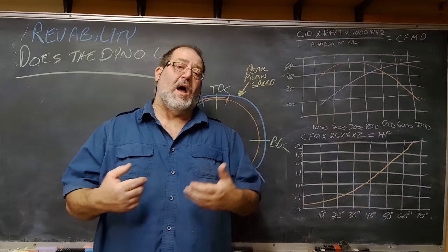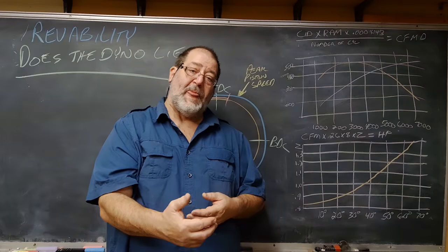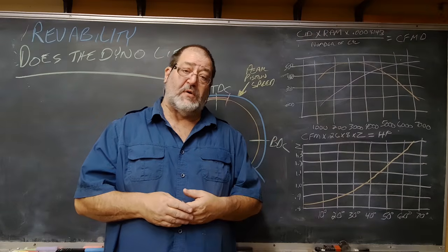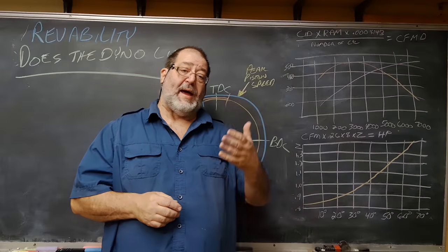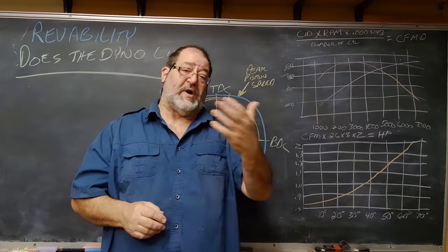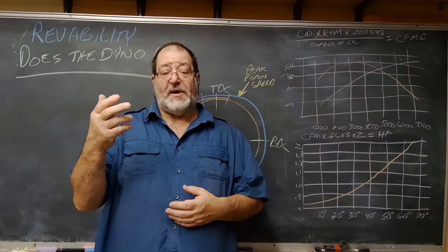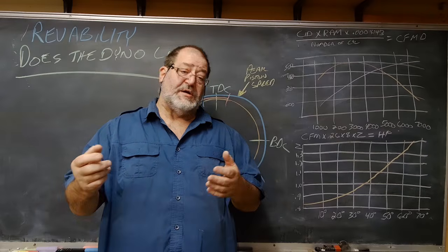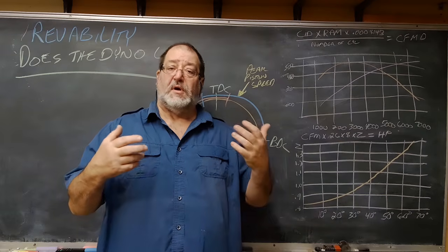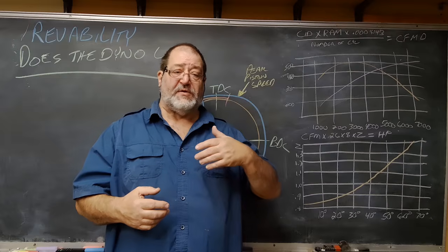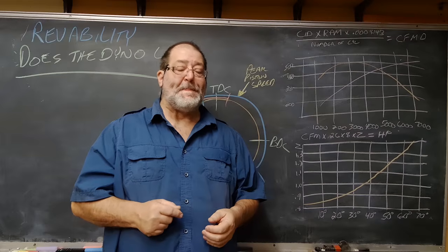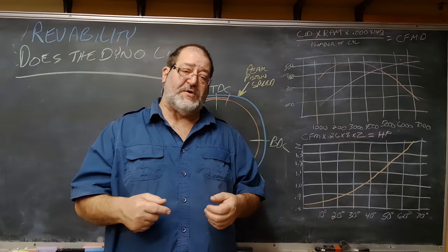Motor was perfect. I put it into a Monte Carlo. Now the Monte Carlo I was building, I built like I build small blocks. 390 rear gear, a Turbo 400, which has a 2.48 first gear, a 2500 stall converter. I wound up having to build headers for the Cadillac just to fit the chassis because the cast iron manifolds didn't fit. Put it in dual exhaust, built it like you'd build a muscle car. You know, it's got a 10-to-1 first gear ratio between the rear and the first gear. And so you got a lot of multiplication.